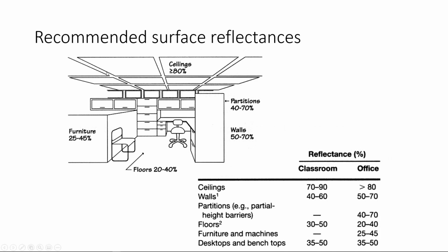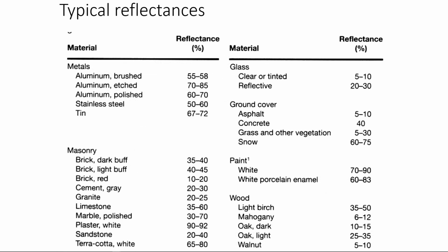And to give you a visual on this, you're looking at a space, you're looking at the things in the space and the kind of reflectance that each has and how that affects the light bouncing around in the room. And many different materials. Some of them have quite a surprising reflectance. For example, you would think wood, oh, that must not be very reflective, but birch could be quite reflective, even as much as a light-colored paint, whereas something like walnut could be extremely absorptive, very unreflective. And these numbers are available in interior design graphic standards or from product manufacturers. And here are some more reflectances. Again, white paint, that's probably going to be pretty bright. But even things like masonry, it can be surprisingly reflective depending on if it's polished and the kind of color balance inside it.